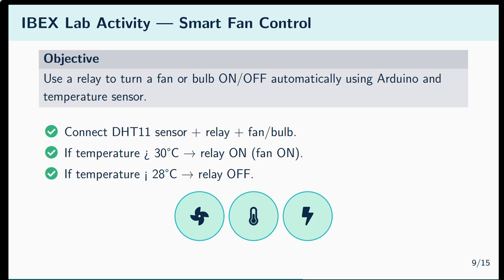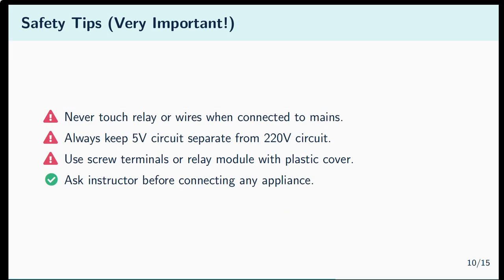You can also use a DHT sensor, a temperature sensor, and so on according to your own need. And if you are going to control a fan based on temperature, like if the temperature exceeds 25 degrees, the fan should start automatically, you need a relay for that as well. We have already discussed all these.